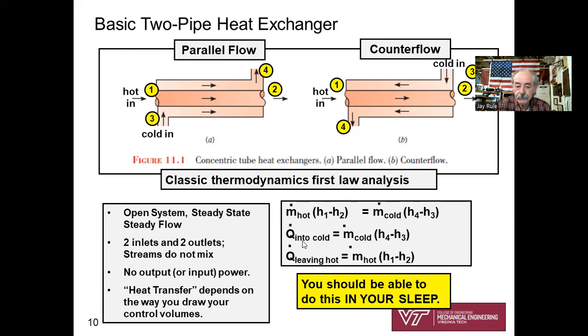Similarly, if you just look at the first law for the cold fluid, you'd see Q dot into the cold is equal to m dot of the cold fluid times (h4 minus h3). And similarly, the heat transfer leaving the hot fluid is m dot of the hot fluid times (h1 minus h2). So my suggestion is you should be able to do this in your sleep.